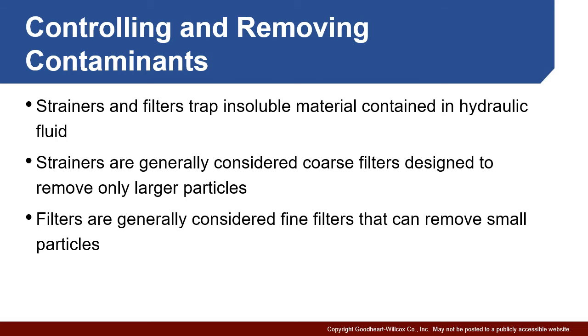In addition, we're going to have strainers and filters whose sole purpose is to trap contamination, right? Essentially, any material that won't break down as insoluble will be trapped in one of these physical filters. Generally, they're broken into two categories. Strainers tend to be relatively coarse filtration, essentially devices with small holes in them where those particles can't go through those holes. They're usually relatively thin material, not designed to hold a lot of contamination, but to prevent any large particles from getting through for physical objects.